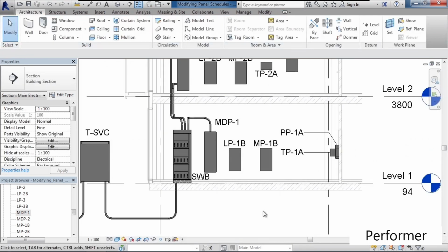So as a review, in this lesson, we looked at modifying panel schedules. We looked at two ways to open the panel schedule for modifying. One is choose a panel first, then click Edit Schedule from the ribbon. The second way was to browse in the project browser in the lower left to the section on panels, and then find that schedule and right-click and open it from there. Once we had the schedule table open, we were able to reposition circuits to different slots, assign different values, spares, if you will. Also, edit the text or font, or the alignment or position of that horizontally and vertically within the table.